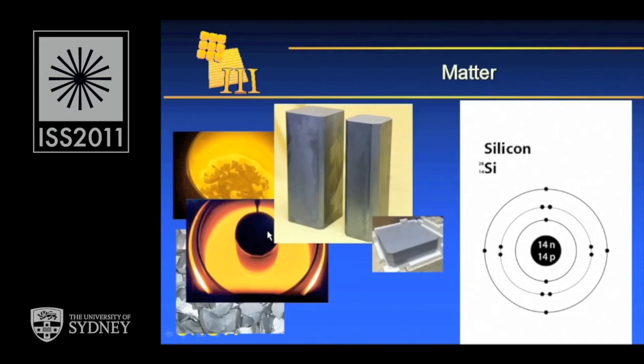And this is what has been used in the past in solar cell work. You take a cylindrical crystal like this, shave the edges off, still leaving a bit of the circular part here, and slice it up like bread to produce quasi-square wafers such as shown here. This is the traditional way of making silicon for solar cells. Much higher throughput, more rugged ways are now the commercial mainstream. This is an area where the technology has evolved very quickly, in producing the silicon in the form of these blocks and slicing them into wafers.